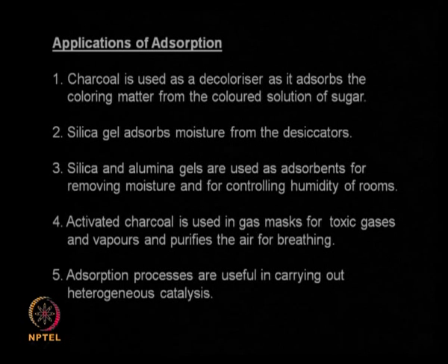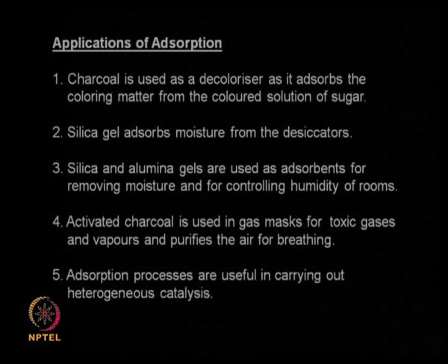Adsorption processes are also used in heterogeneous catalysis. Suppose I am doing a hydrogenation of oil using a nickel catalyst, the hydrogen is in the form of a gas, nickel is in the form of a solid, and your oil is in the form of a liquid. So what happens? Hydrogen gets adsorbed on nickel catalyst and then it reacts with your oil to hydrogenate the oil. So there adsorption becomes a very important phenomenon, and the rate at which the hydrogen gets adsorbed on nickel plays a very crucial role in the overall rate of reaction, and if you can improve or enhance the adsorption capacity of nickel, then the process becomes very economical because you will be using less nickel.